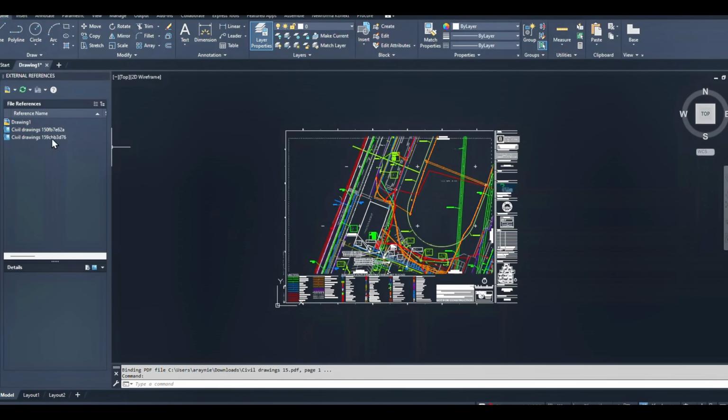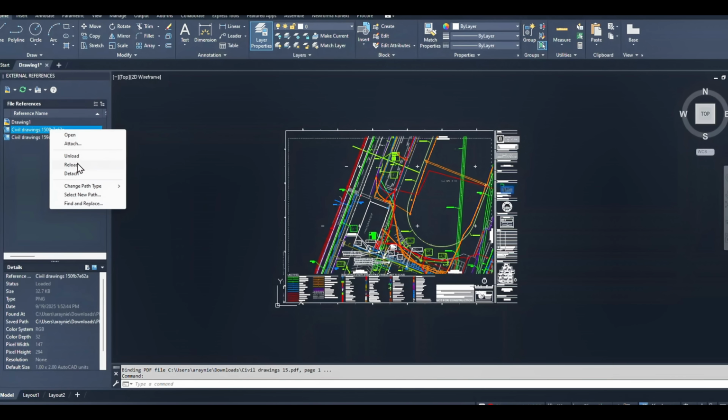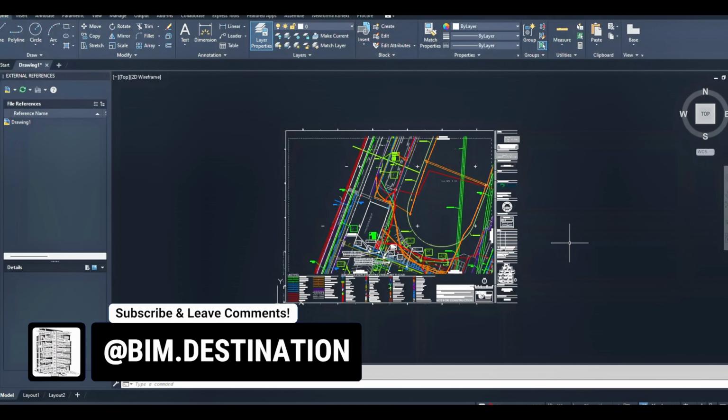I don't need it at all because I have my own drawing. So I just created my DWG file from CAD, and everything is coming in correctly. These are all the reference files that were attached to this, so I can detach all of that as well. It's just a logo. So there you go. It's cleaned up. This is the PDF turned into a DWG.